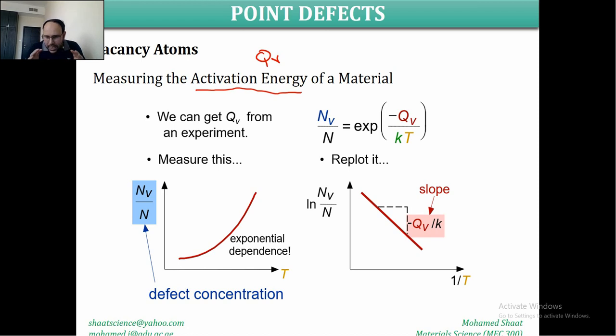Again, we observe these atoms inside the material structure through the TEM, then count how many vacant atoms are located within this area. This area should include a certain number of atoms if it were perfect. But anyway, there should be a certain number of vacant atoms. So we count how many atoms exist within this TEM image, and then how many vacant atoms exist.